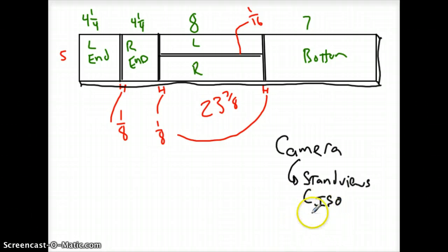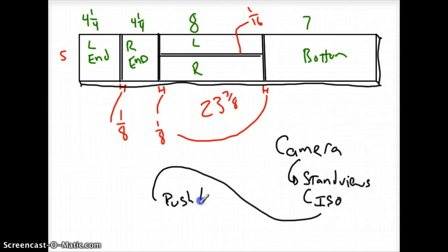That goes to 3-dimensional view. From there, use the push-pull tool to pull that whole piece up 1/2 of an inch.